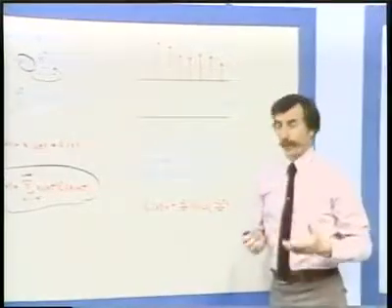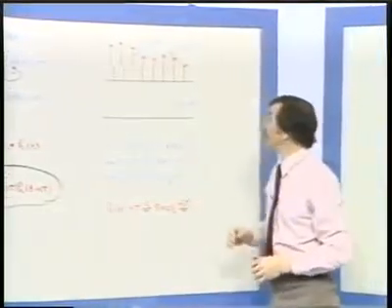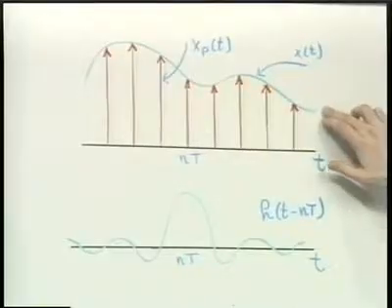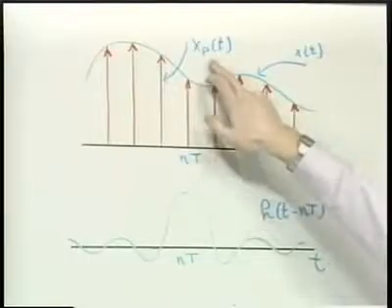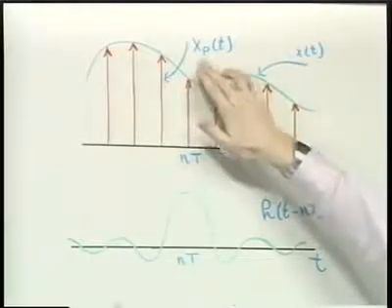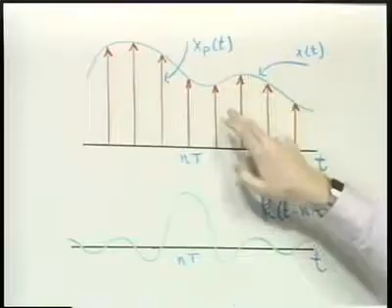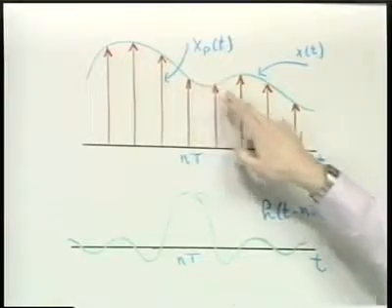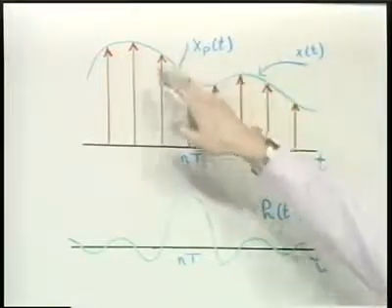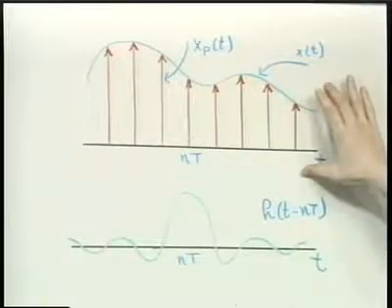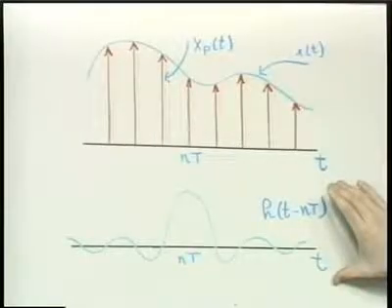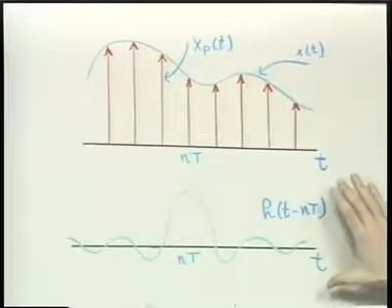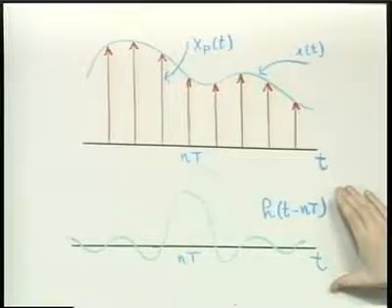In terms of a diagram, we can think of the original waveform as I've shown here, and the red arrows denote the sampled waveform, or the train of impulses whose amplitudes are the sample values of the original continuous-time signal. Then I've shown here what might be a typical impulse response, particularly typical in the case where we're talking about reconstruction with an ideal low-pass filter.